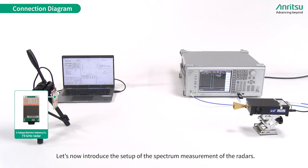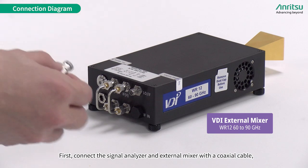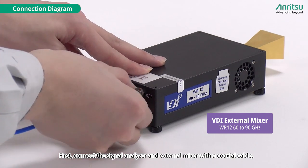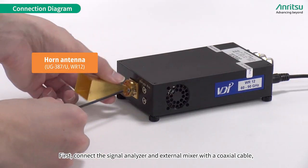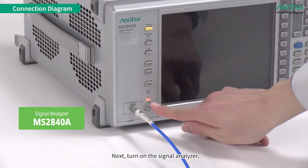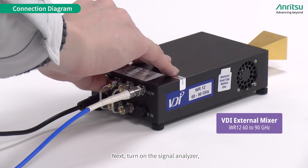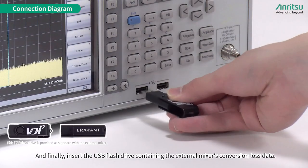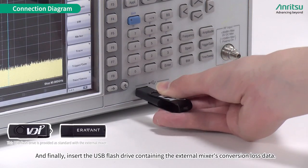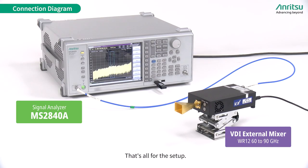Let's now introduce the setup of the spectrum measurement of the radars. First, connect the signal analyzer and external mixer with a coaxial cable. Next, turn on the signal analyzer. And finally, insert the USB flash drive containing the external mixer's conversion loss data. That's all for the setup.